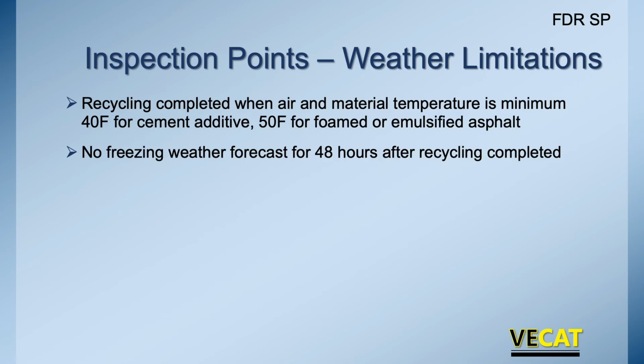A few other things, weather is critical. We can't do this when it is too cold. So we're looking at air and material temperatures. If we're doing a cement additive, it's 40. If we're foamed or emulsified, it's 50. Years of experience have shown these are the minimums. We've tried projects and we've played with the weather, and it hasn't been nearly successful. So in the specs, that's why we have 40 and 50. And we don't want any freezing weather.